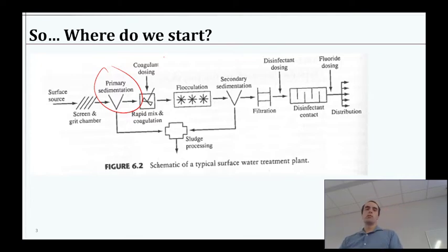And so then after that, we'll do sedimentation a second time and collect all the sludge and junk, process that, probably dewater it, send the water to wastewater, and just landfill the solids. And then move on with our different treatment steps. So sedimentation is what we're talking about today.